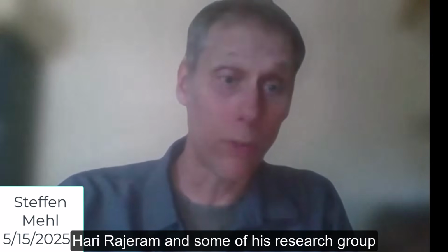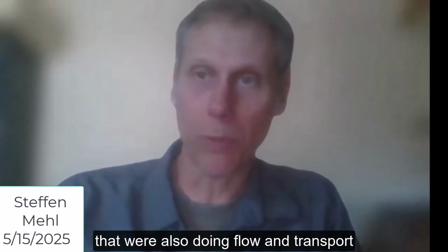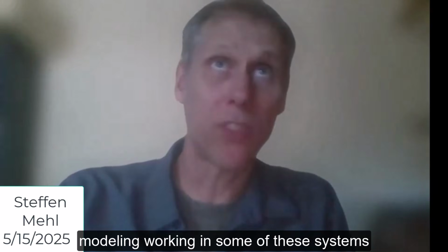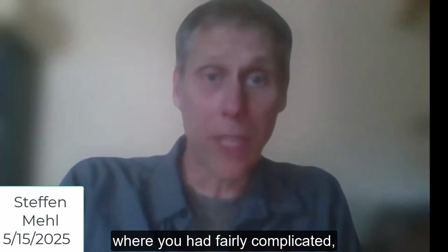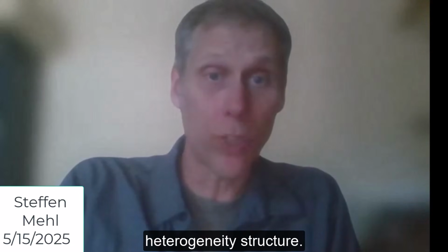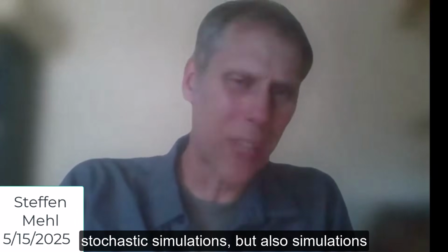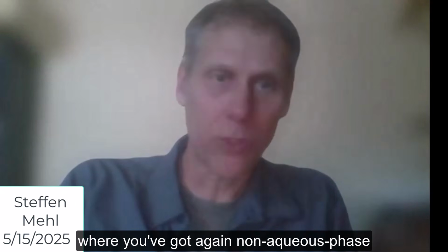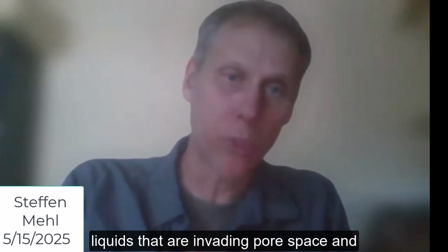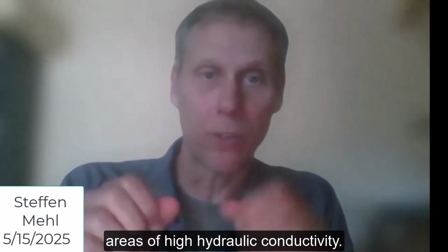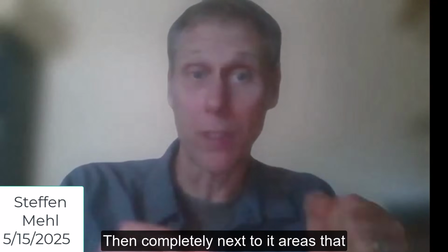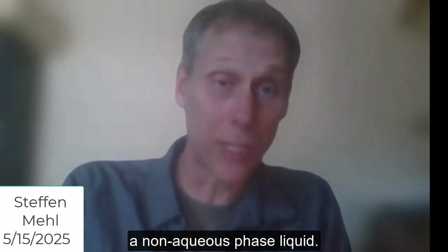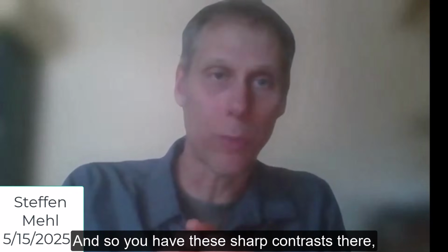I was working with Professor Hari Rajaram and some of his research group, who were doing flow and transport modeling in systems with fairly complicated heterogeneity structure. They were doing a lot of stochastic simulations, but also simulations with non-aqueous phase liquids invading pore space and blocking it. You have areas of high hydraulic conductivity right next to areas completely blocked by a non-aqueous phase liquid, so you have sharp contrasts.